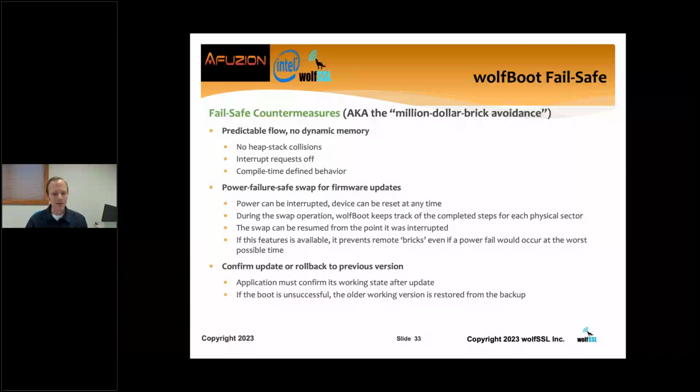We can also roll back to a previous version. So once wolfBoot is booted into a new image, it gives the application the opportunity to confirm that it looks okay. If it doesn't, wolfBoot will just roll it back to the previous image.